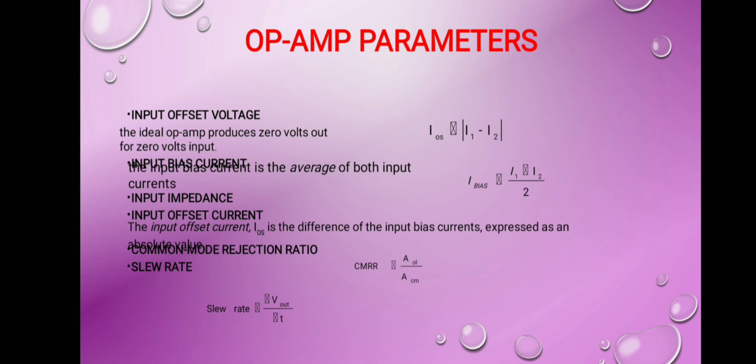If we require the slew rate, that means output change with respect to the input, then the parameter to concentrate on is the slew rate. Means we require to choose that type of operational amplifier where the slew rate is high. In that condition, other parameters have less importance. Similarly, for other applications, as per the requirement, we choose the particular operational amplifier and find the different applications.